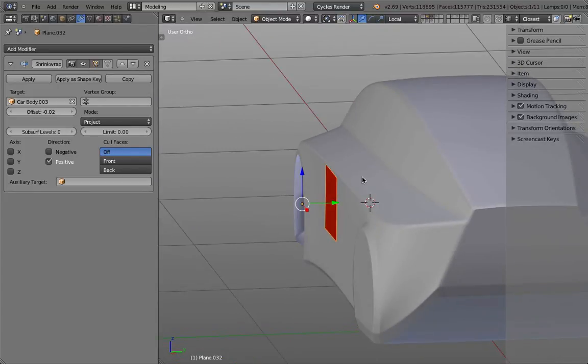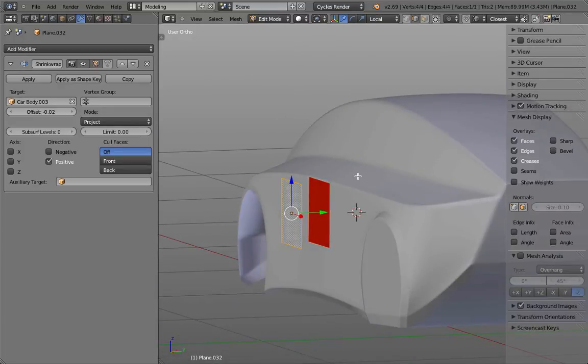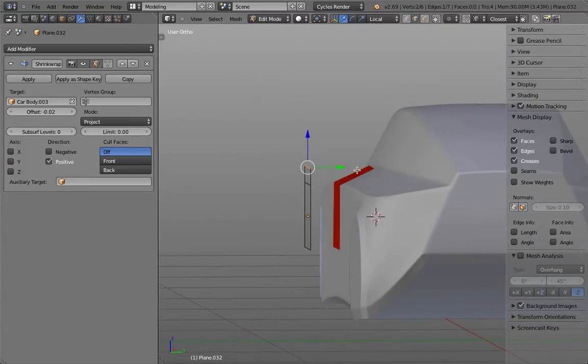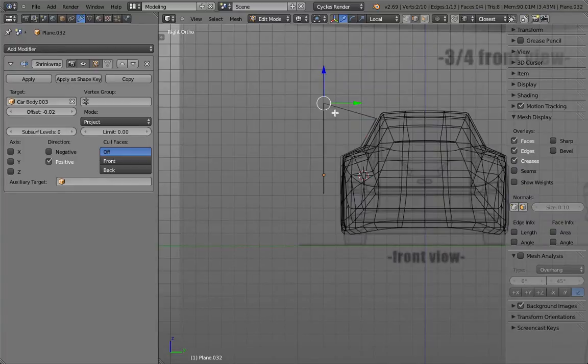Okay, so this looks not too bad. So let's say I select this upper edge and I extrude something out. And maybe I extrude something further out. You see that actually it flows over it. And if I now extrude something out another time, you see that at one point the software gives me a bad result. And that is because actually you can see if you follow the Y arrow, there is nothing there.